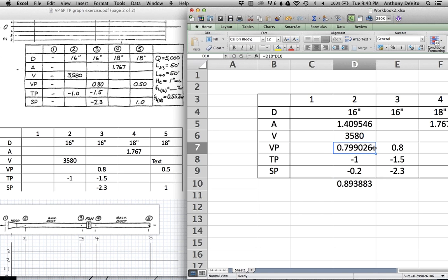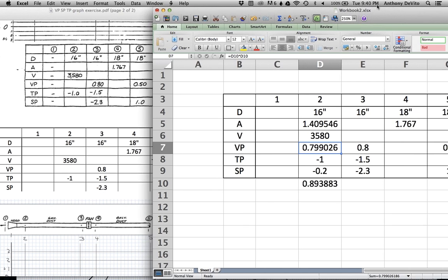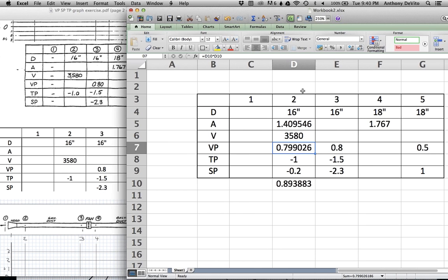Okay, so now in the next segment, in order to achieve that, we're going to have a larger negative pressure here. Notice the velocity pressure we just calculated was 0.8. Notice what the velocity pressure is at 0.3. It's the same. Makes sense, right? We expect the velocity throughout to be the same unless the duct diameter changes. So our calculation here is right. In fact, we didn't even really need to make this calculation. We could have just looked there and realized it had to be the same.